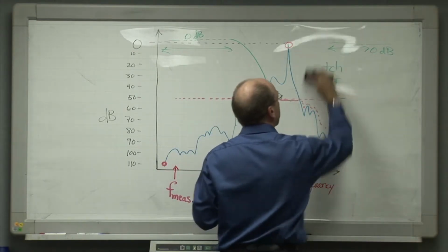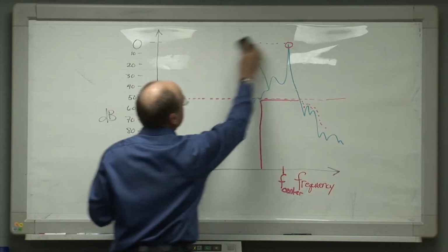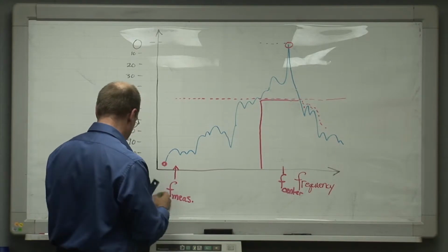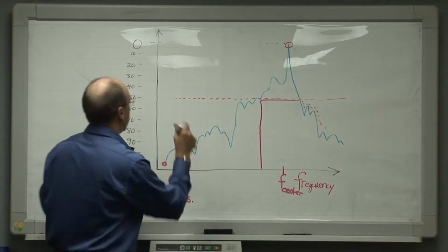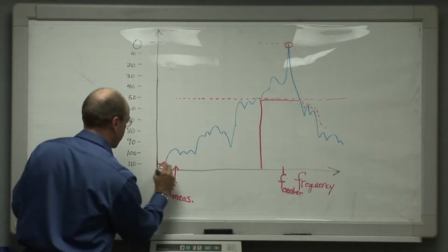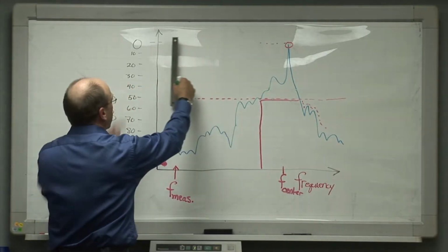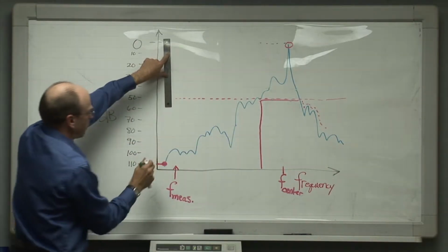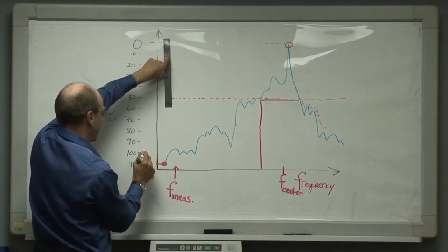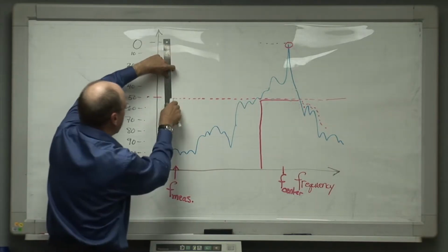We go ahead and remove the notch, and then we take the spectrum analyzer at its input and we insert attenuation. And how much attenuation would we need? Well, if this was the measurement system noise floor right here, and we want to measure this level up here, we need to put in enough attenuation to bring the spectrum analyzer's noise floor up to about this point right here. And that's going to be 10, 20, 30, 40, 50, 60 dB.